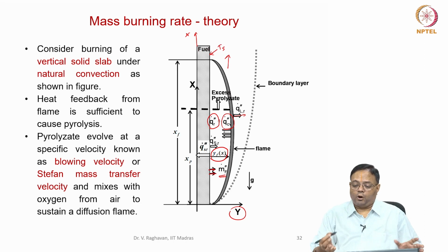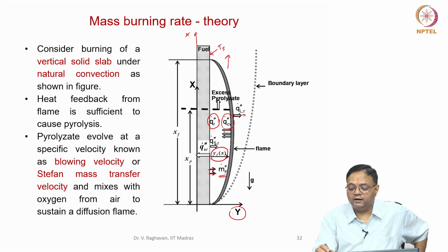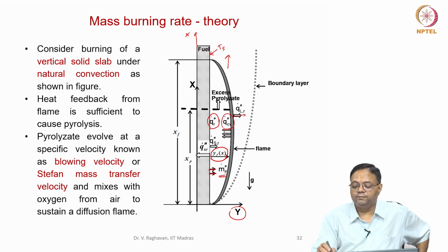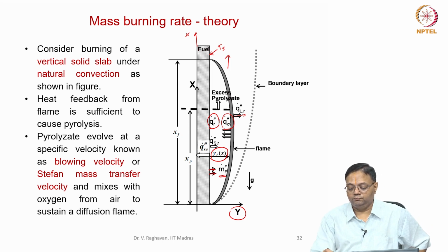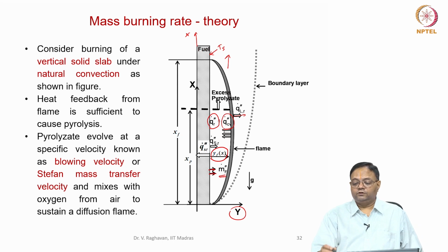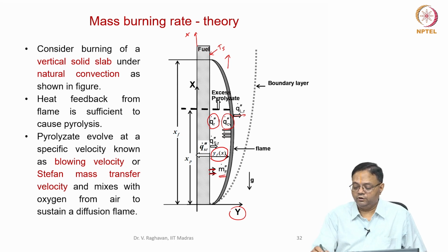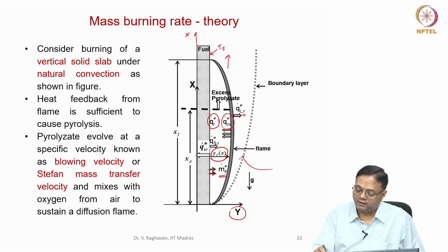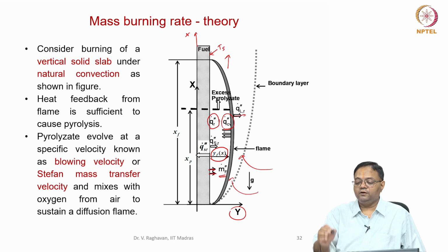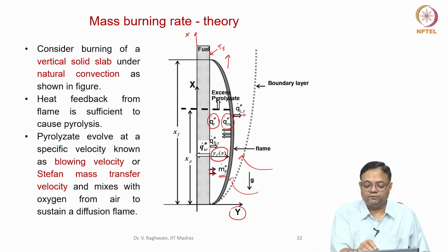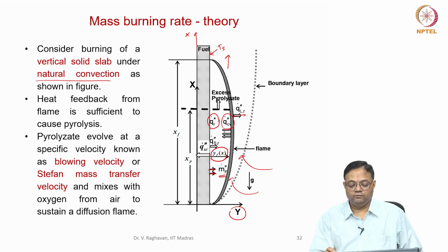So, probably if the heat release rate is there, about 30% or 35% comes into the fuel surface, and a steady burning occurs consuming the fuel. Okay. So, this is the one where the gravity is in this direction and the entrainment occurs in this direction. So, this is basically the natural convection which is induced in this. So, the heat transfers are several.